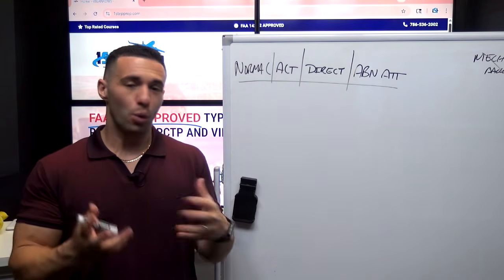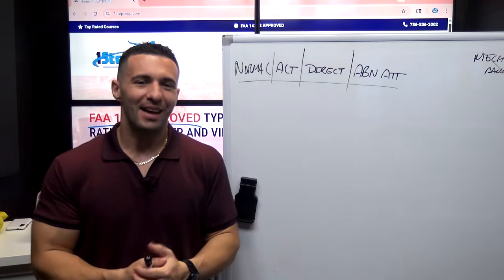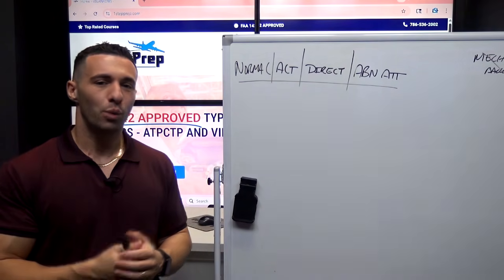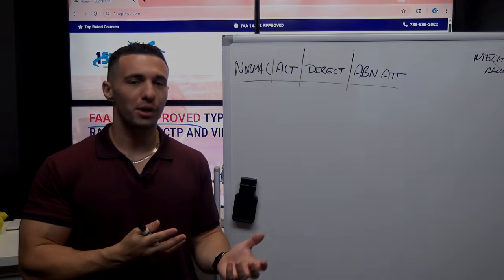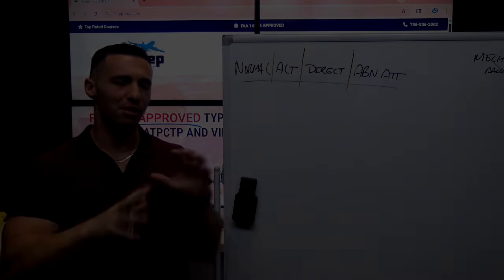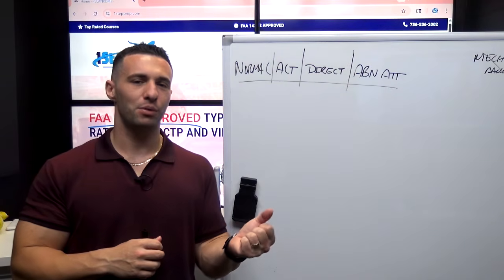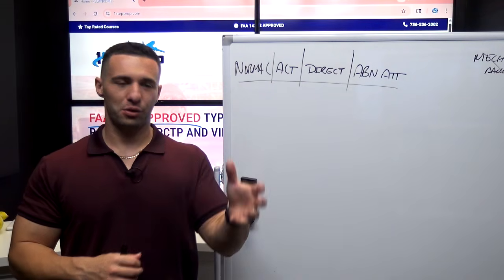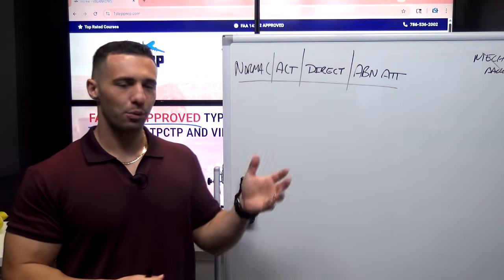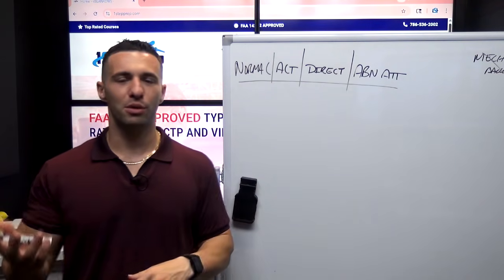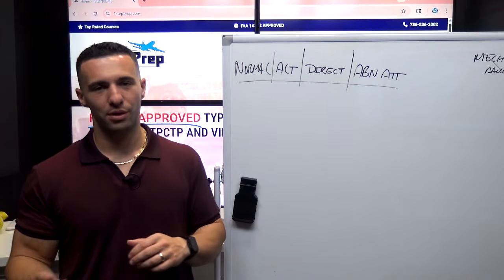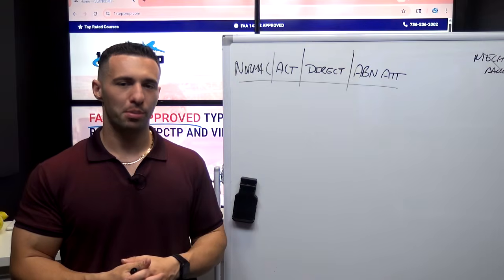And then once you finally fix it, it does kind of leave you in an alternate law with the G-load protection. So you do recover the G-load protection. There's been some discussion around this I will share, because early manuals of the 320 said in abnormal attitude law, and I have screenshots of this to validate it, basically that we do retain G-load protection, but the more recent versions of the manuals that I have seen say that the G-load is returned after we recover to a normal pitch attitude.